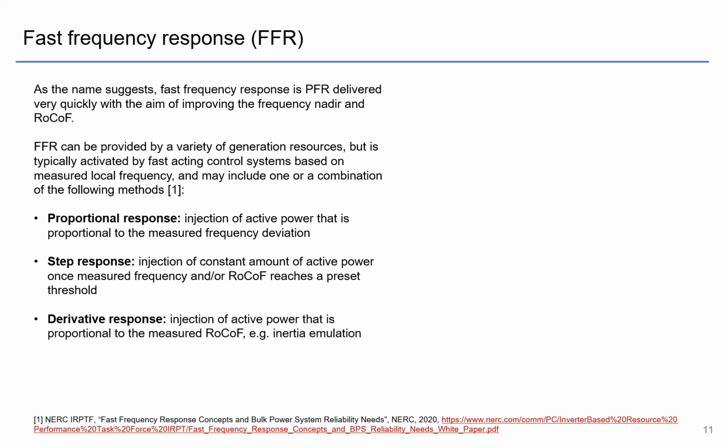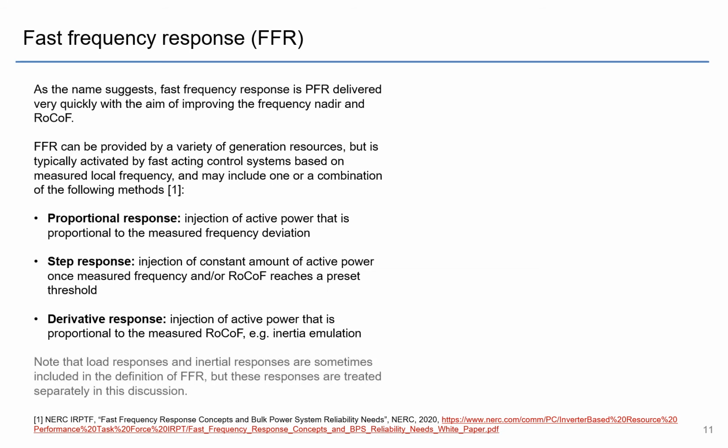And a derivative response is where the injection of active power is actually proportional to the measured RoCoF. It's like inertia type emulation. So note that the load responses and inertial responses are sometimes referred to as FFR, but these responses are treated separately in this discussion.